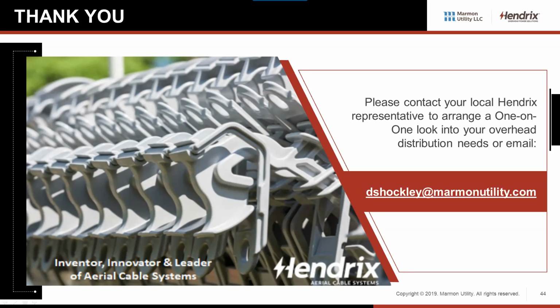Our recommendation is, since it's not fully insulated cable, we don't want trees coming in contact with it all of the time. So our rule of thumb is, you want to trim the trees back. They can brush up against it, they can fall on it, and that's fine. We just don't want them to come in contact with it all the time.